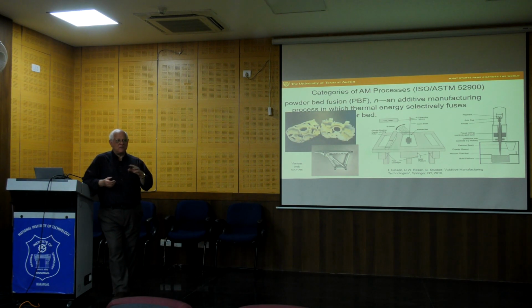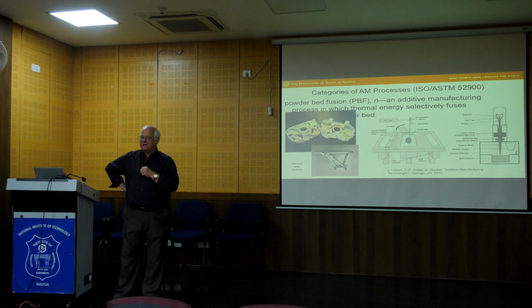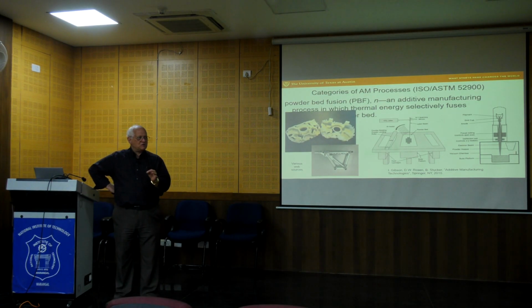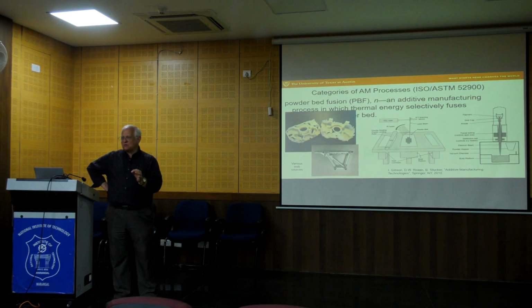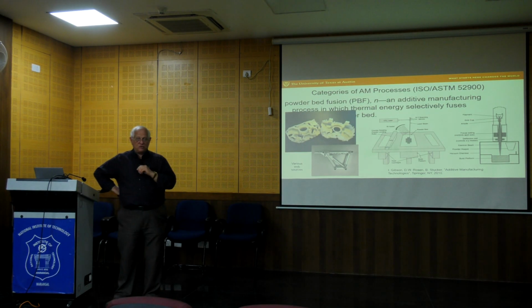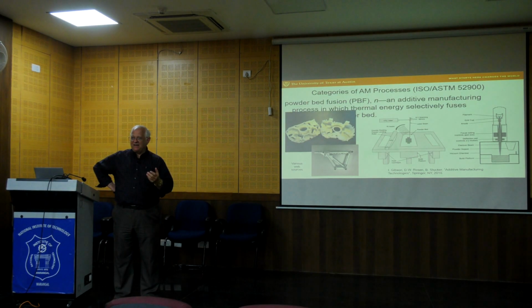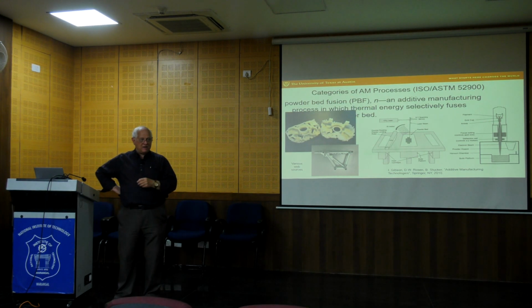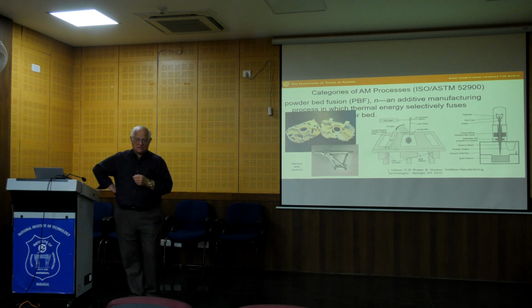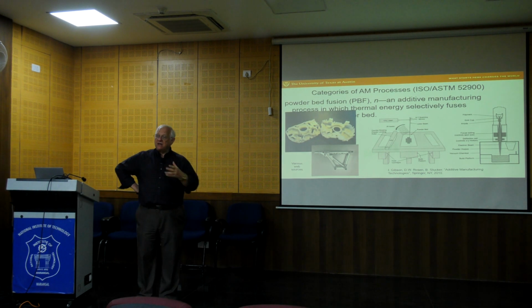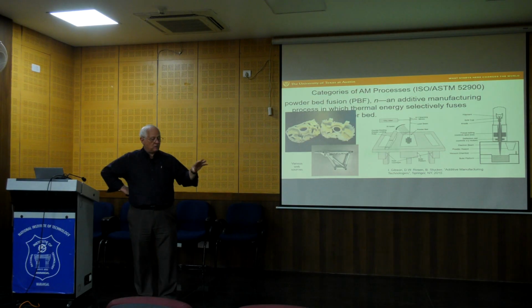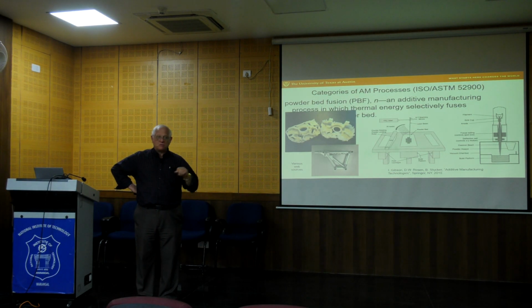It turns out, I've covered material extrusion. It turns out that one of the rules of material extrusion and powder bed fusion is the polymer feedstock. If it works for one technology, it generally does not work for the other. So, for example, ABS and polylactic acid for the extrusion machines, as well as the polyimide, the ULTEM material, those are all amorphous polymers.